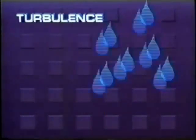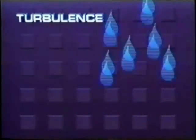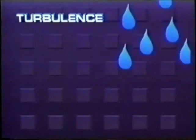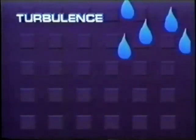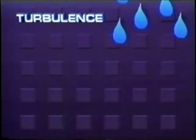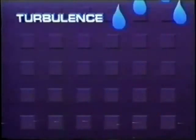The Bendix Arinc 700 series radars, when equipped with the Doppler turbulence detection option, are capable of detecting and displaying storm-related turbulence in addition to the rainfall rate display. Turbulence within a rainstorm causes the raindrops to travel in a very erratic path as they plummet toward Earth. The turbulence detection radar identifies these areas of moderate to strong turbulence by measuring the change of the horizontal raindrop velocity from one transmitted pulse to the next.